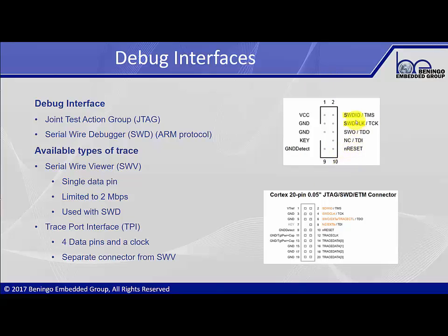As part of this, though, we also have our serial wire debugger. We also have our serial wire clock. And you can see here this SWO, which is another serial wire output that can be used with the system viewer. A lot of the ARM parts are going to have serial wire debuggers built into them by default. And that's really probably the most common interface I think that I use when I'm going to be debugging an ARM-based microcontroller. But there is also support for things like the typical JTAG that we're all familiar with.